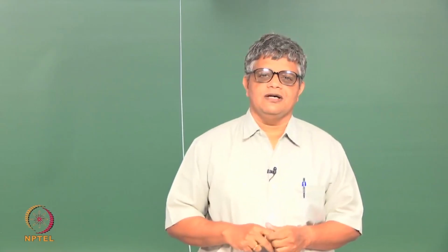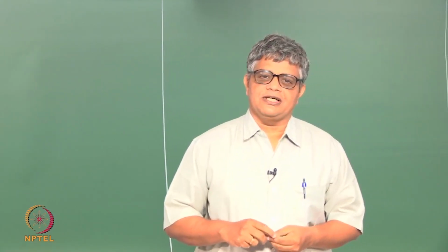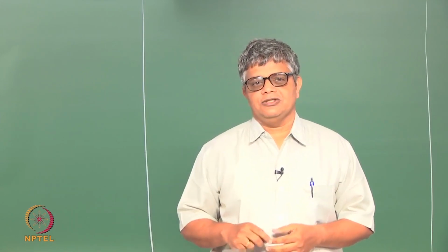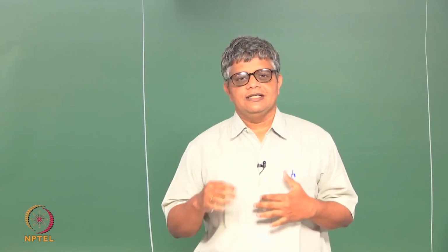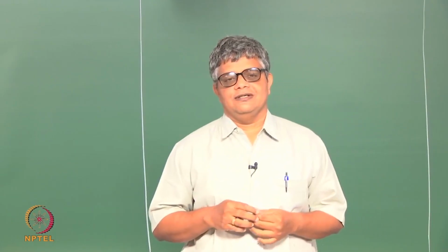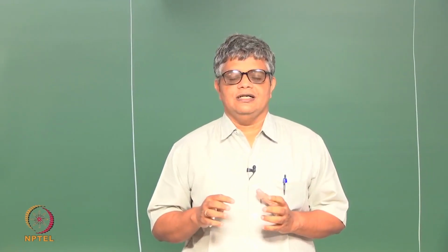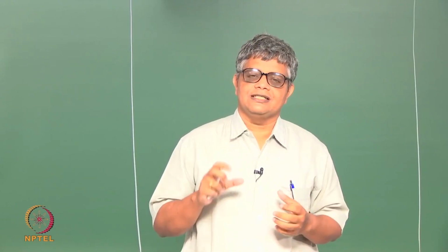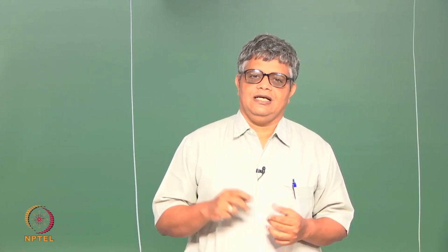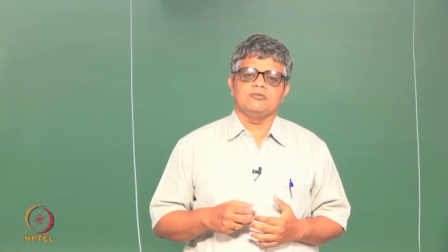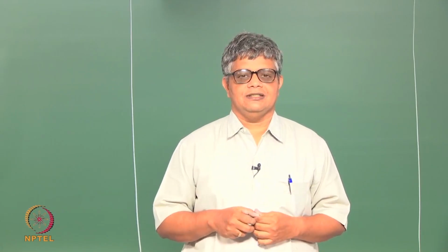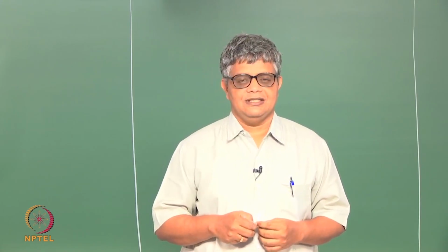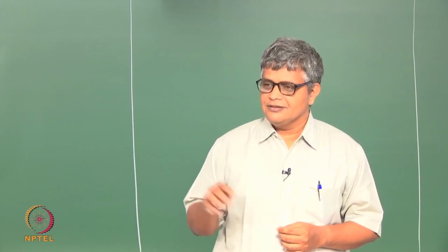In the last lecture, we have looked at the pressure correction equation method approach. In today's tutorial class, we will derive the elements of each of these. We will start with the x momentum balance equation, and we will try to come up with a discretized equation which can be solved provided we know the pressure from the previous iteration and things like that. Okay, let us start again.